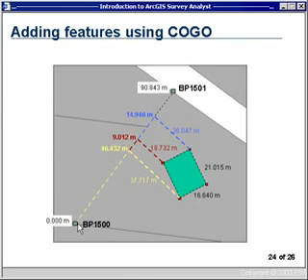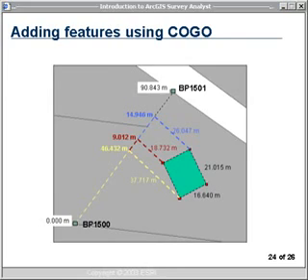So we go down that distance and over the offset to that building corner. From that point, we go an additional 9 meters with an offset of 18 meters to identify that point. And then finally, the third building corner is identified by an additional stationing of 14 meters and an offset of 26. That will help me identify those 3 building corners. Then lastly, this fourth building corner, I have distances down to that corner from 2 known points that we've just completed. And I'll use a distance-distance intersection to identify those.